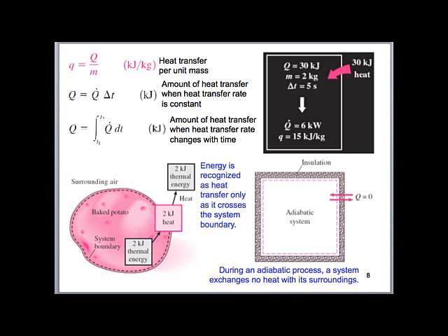That temperature difference can remain constant after we have some process occur, and we would still be having heat transfer from system to surroundings. So even though the process was isothermal, doesn't necessarily mean that heat transfer is not present. So be very careful. Isothermal means no temperature change. Adiabatic means no heat transfer to or from the system.